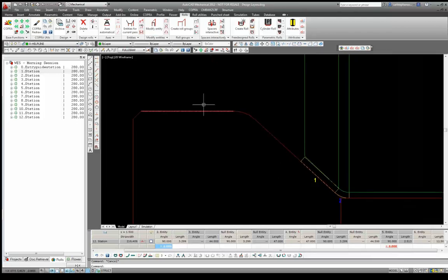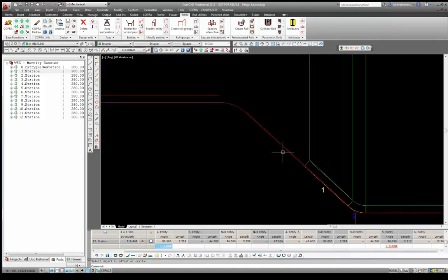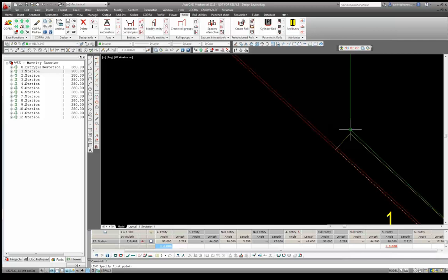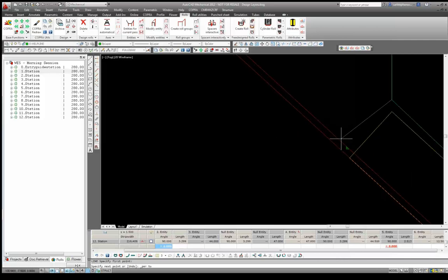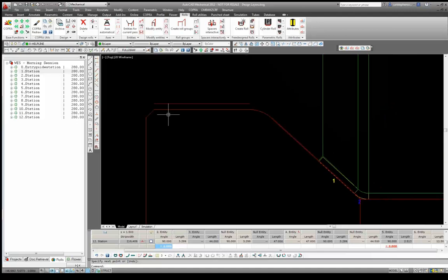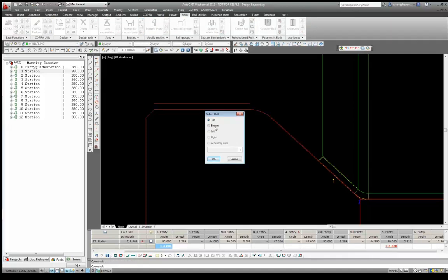So first of all, I'll do some offsetting here, just a material thickness offset, and a running clearance over here. And then what I will do is draw a line from here to here, and this will be my control of the strip edge. So now to create entities with crosshairs, we're asked for which axes. In this example will be the top.